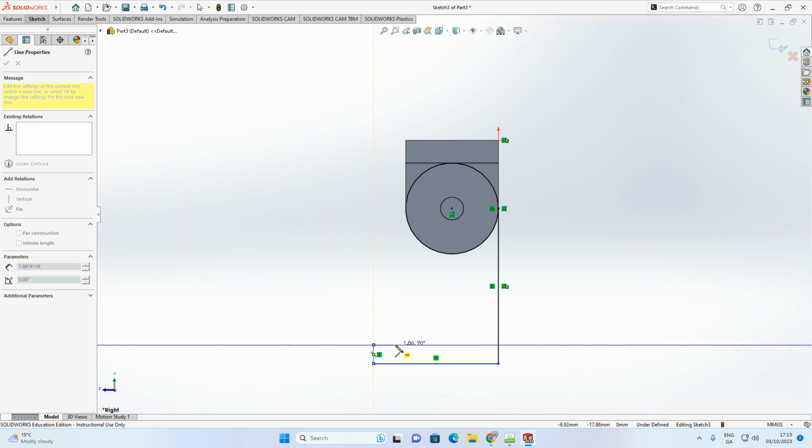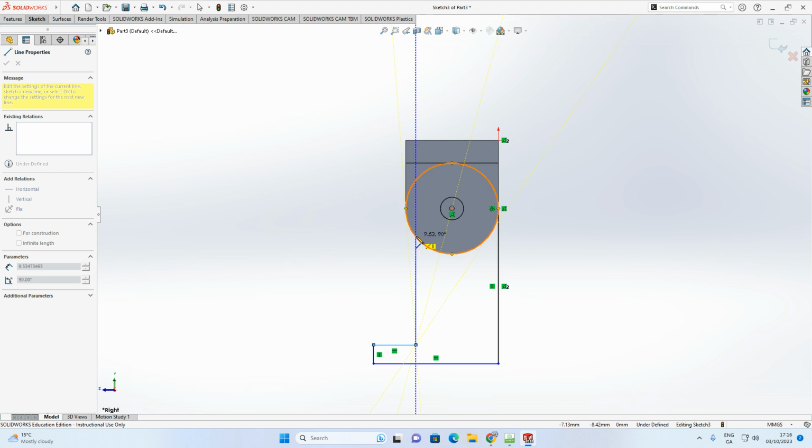Click, drag in. Make sure this time we don't map onto it. We go a little bit further in than we need. Don't leave it out. Click. And now we're going to go straight up, and when it hits the outside of the circle in a vertical position, click. Press escape to deactivate your tool, top left button on your keyboard.